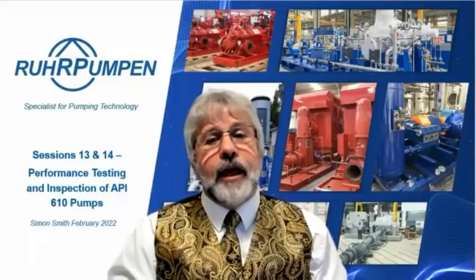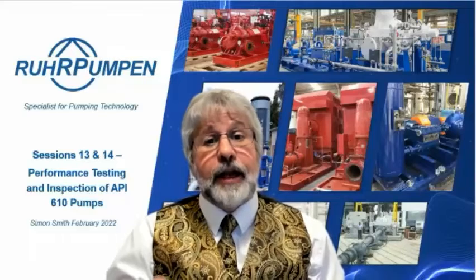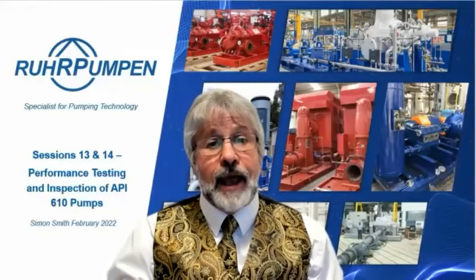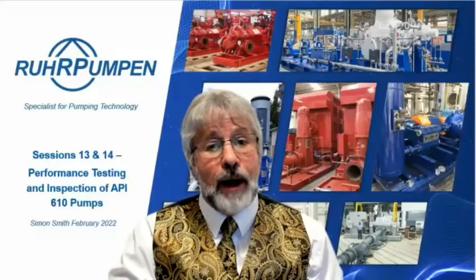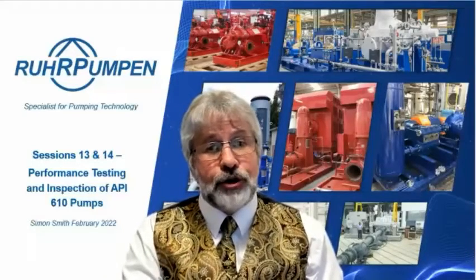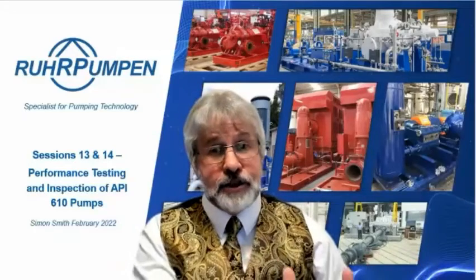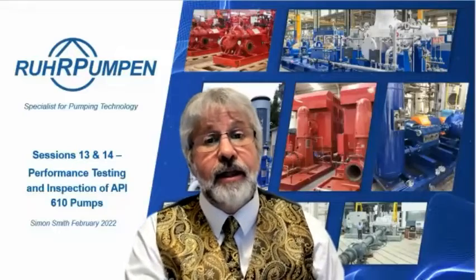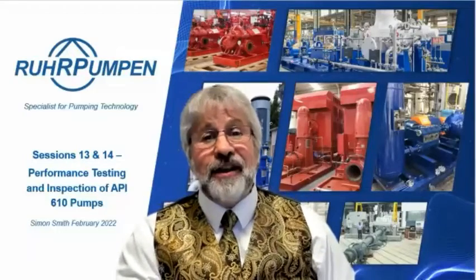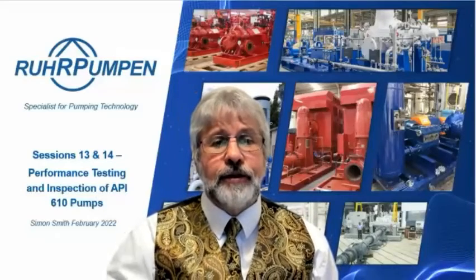Yes, I think the seal gland plate is part of the mechanical seal and it will be hydro tested at the mechanical seal supplier. When we carry out a hydro test of the pump, there will be a blanking plate put across where that seal flange plate would be. So we're hydro testing just the pump casing and cover bolted together. The seal flange will be tested at the seal vendor.